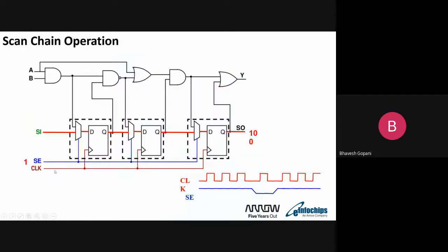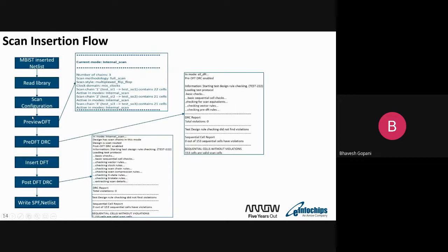Then how the reset is controlled. Each and every flop has a reset. The reset might be coming either directly from the top level, or it is generated through some logic. So those scan resets I also need to define here. Then there are scan related parameters and compression techniques.